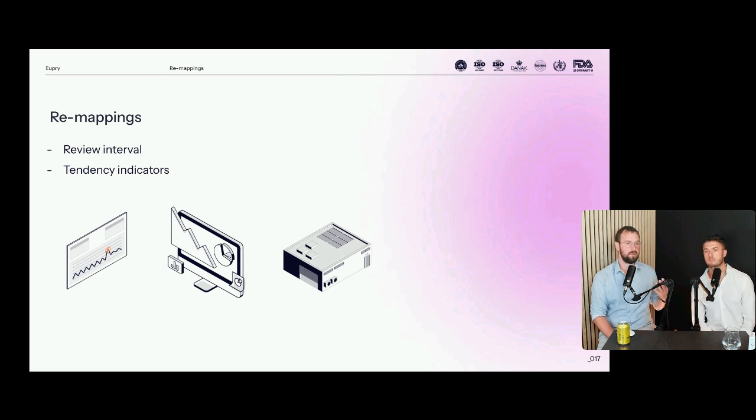Have you performed any changes of the HVAC system? Has there been ongoing changes to doors, gates? The sealing: one of the issues we often see is that the seals on fridges and freezers degrade over time. So have you performed regular maintenance on those? If not, there's a greater chance that you will have to perform a remapping, because there's a greater chance that the temperatures are non-conformant.